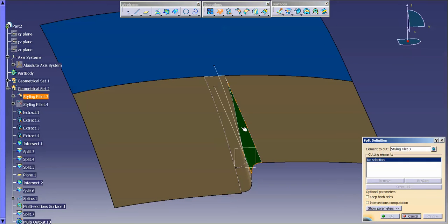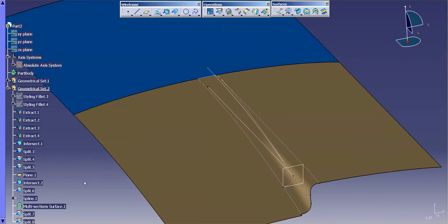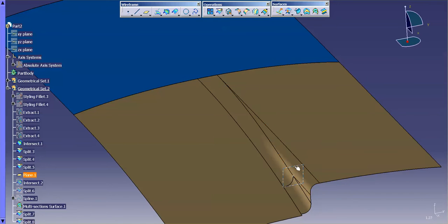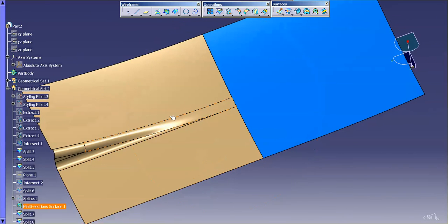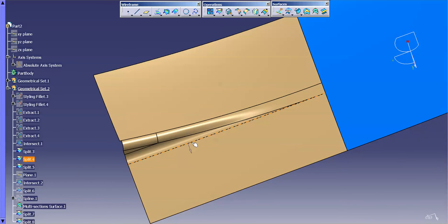That, split here to here. I've got those split, I've got all those split. Let me go ahead and hide all my curves. We'll go Tools, Hide, All Curves. We'll hide this, and we'll hide that. So here you can see that now this comes in and transitions out. This is a complete surface. It doesn't go off to a point.